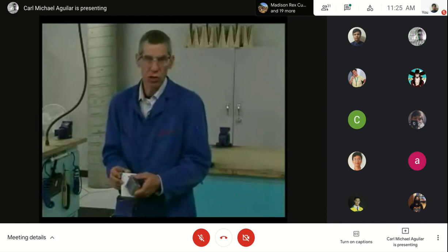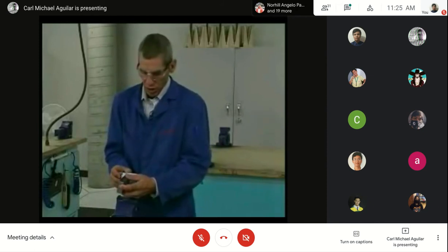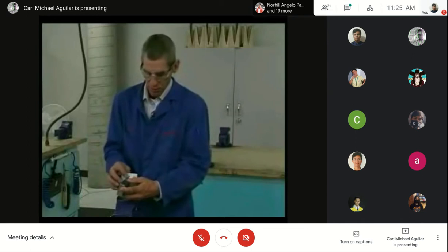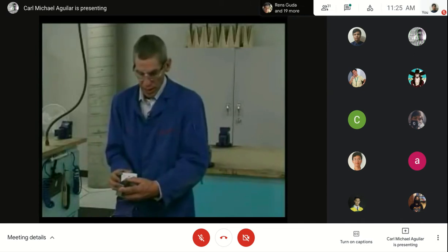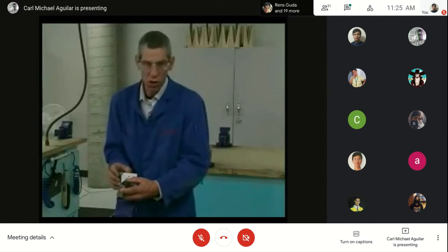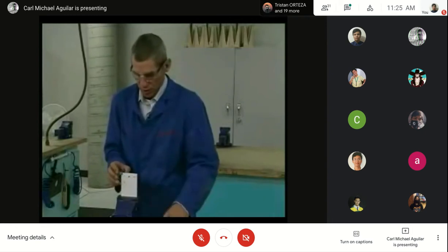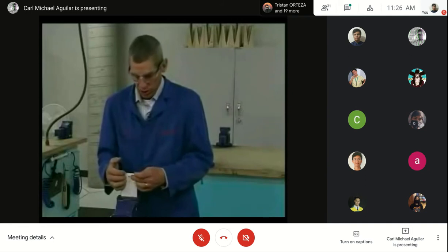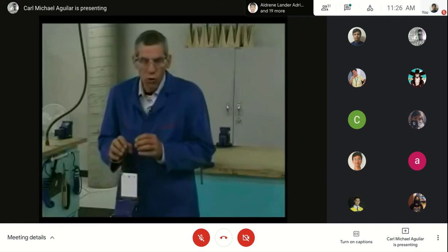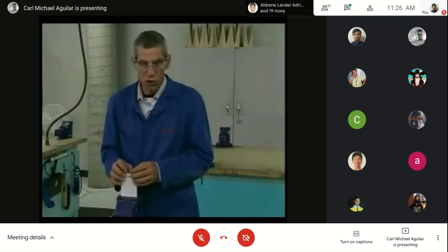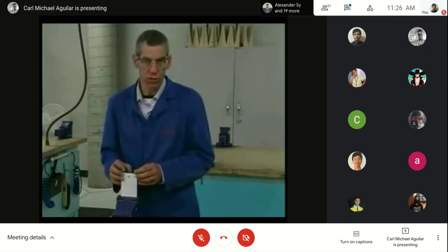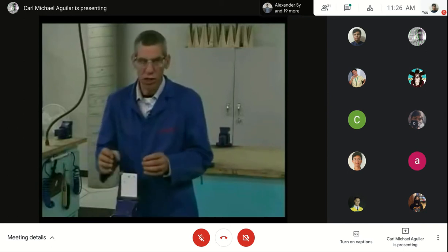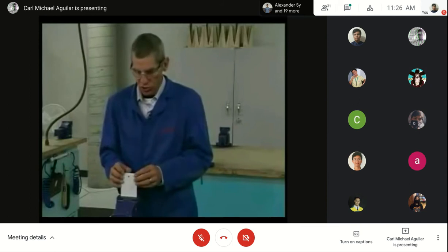The sheet damage can also occur when the bucking bar comes off the shop head and the riveting gun is still going. That will cause sheet distortion or bucking bar marks on the back side of the sheet. Over riveting too much can cause sheet distortion. Because the rivet is swelling out too much, it causes the sheet to start distorting.